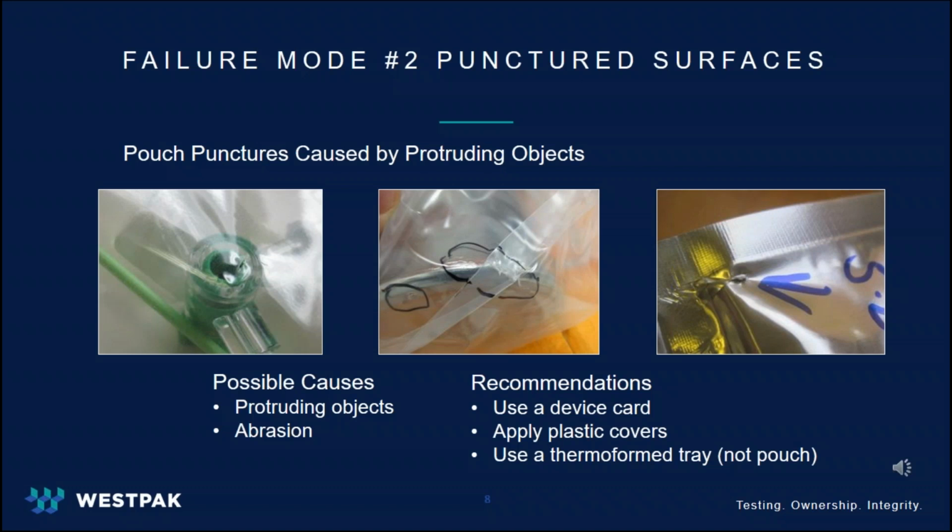We recently had a customer that had a device that looked like a small trash can with sharp feet on the base. They originally had it in a nylon Tyvek pouch. It failed the first round of gross leak testing after transit testing. We recommended putting it in a tray. They decided to double pouch the unit instead, reran the test, and had gross leaks on both sets of pouches. They finally went to the recommended tray, and it passed with flying colors.